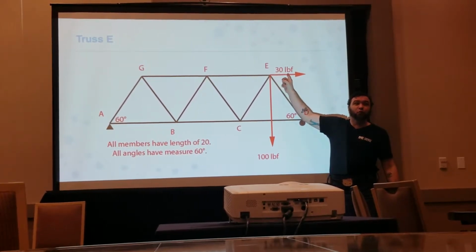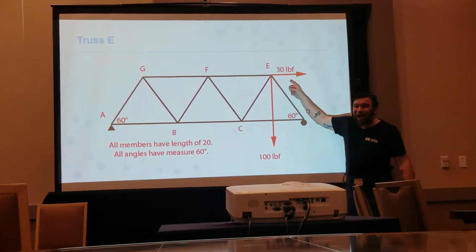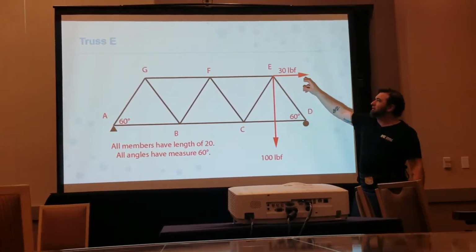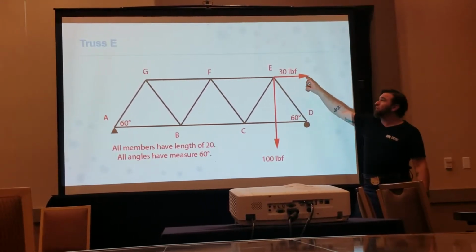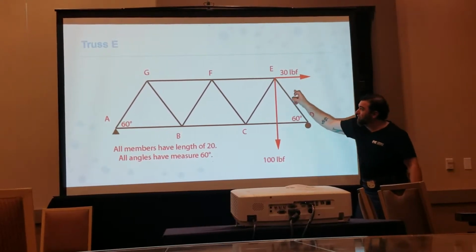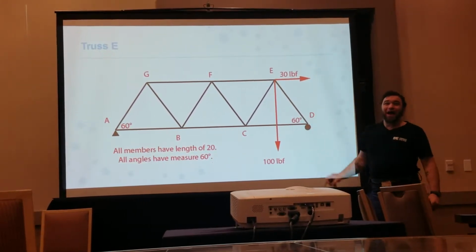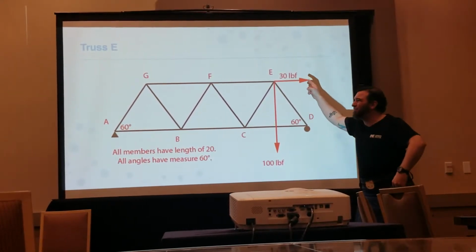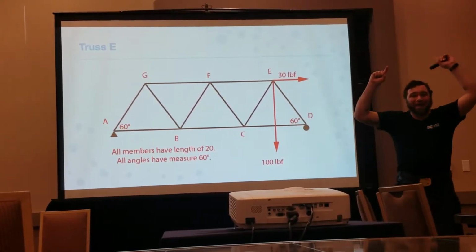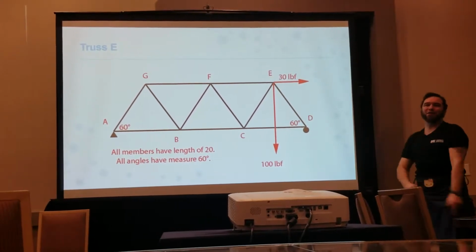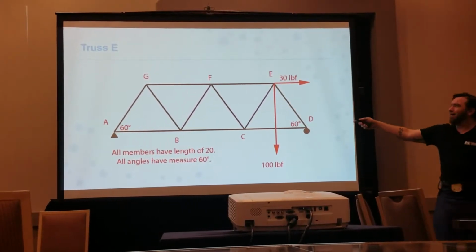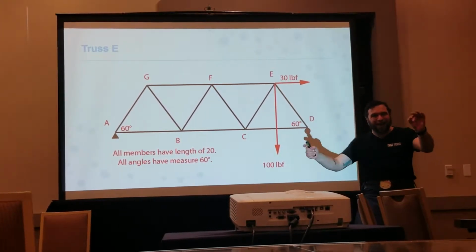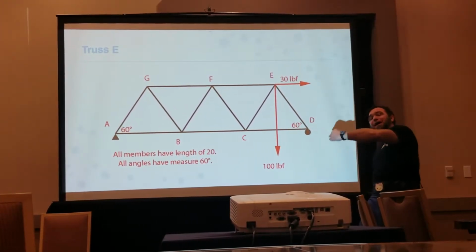So you would have to do some weird calculation to figure out the angle from A to E, and then calculate the component of 30 over to that weird angle, and then you multiply that component force times the distance from A to E, and you get the exact same number as 30 times this height. You get the exact same number and in the exact same direction.